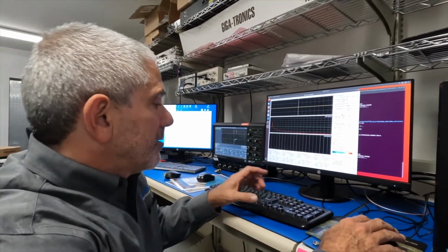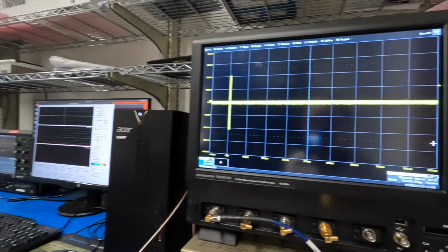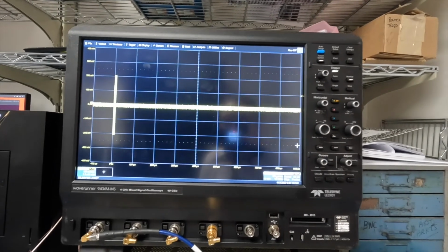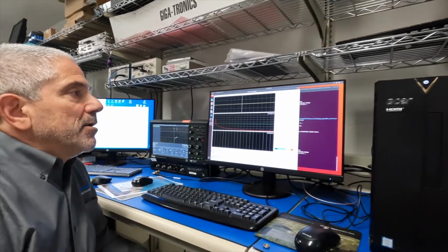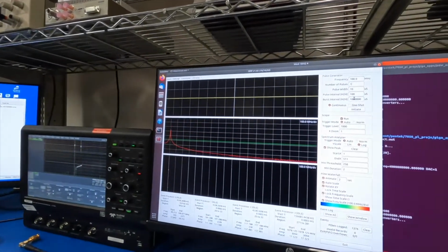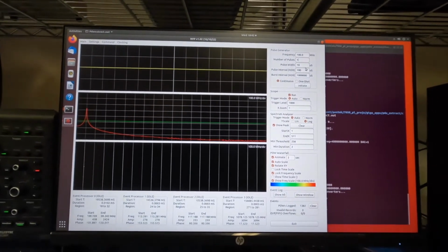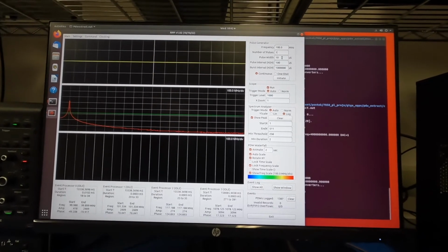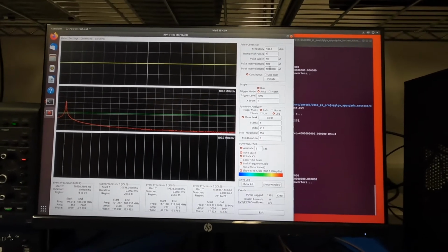So we're going to start really simple. We're just going to do a very simple pulse train of just 1 pulse per second and a set pulse width and PRI and center frequency. So the top of the GUI right here just allows us to create the RF out of DAC channel 4 with all of its pulse parameters, and then we're going to analyze that with the rest of the GUI. So for right now, we're putting out 1 pulse of 10 microsecond pulse width and a 100 microsecond PRI, and it has a dwell of 1 second, or